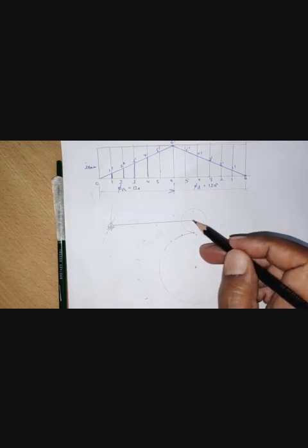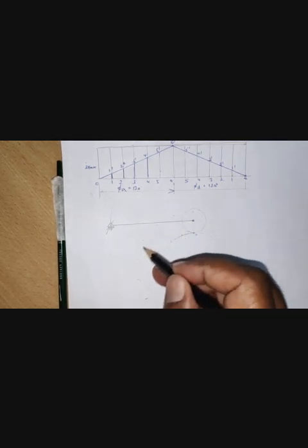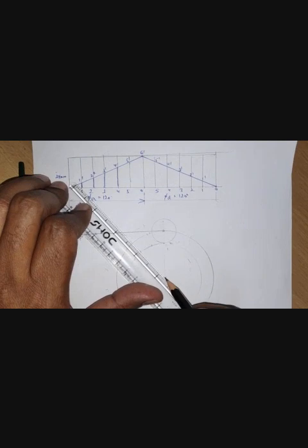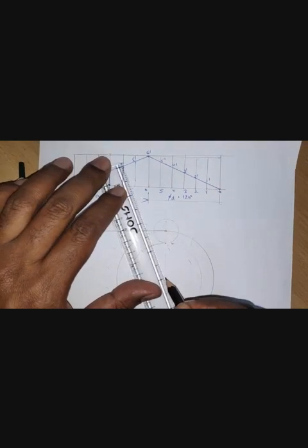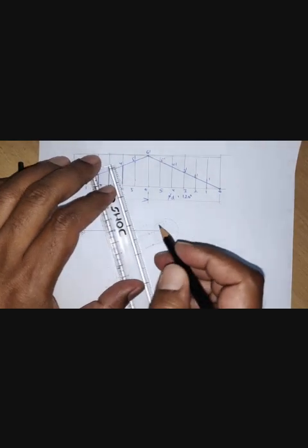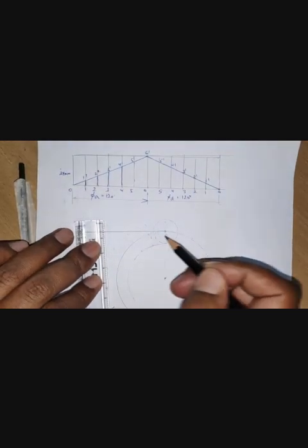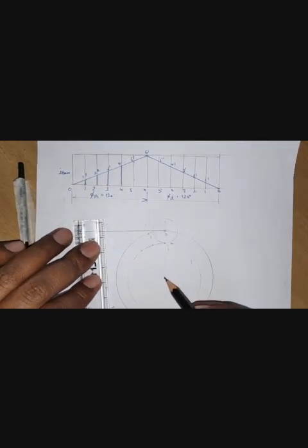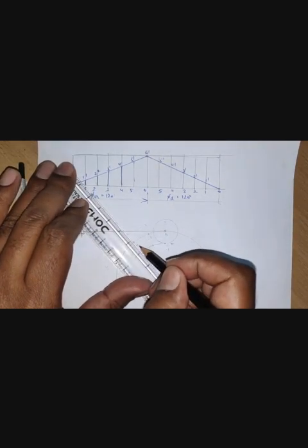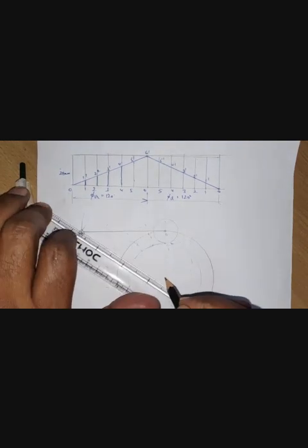So what we should do is draw a circle passing through this, which is called the prime circle. Each of the lines drawn for 20 degrees, where it cuts the prime circle, let me call this starting point 0, this point 1, and the next point where it cuts at 40 degrees as 2, like this. All these are marked on the prime circle like this.